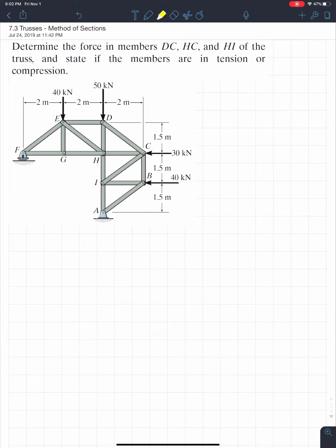That principle, specifically, is that when we analyze a joint, we want to create a free body diagram of that joint. So we cut all of the members around that joint. What you're going to see in the method of sections is that we do the same thing. We're going to cut the truss, and wherever we cut, whatever members we cut through, we replace those members with forces. Then you get a nice free body diagram with a bunch of forces based on the members that you cut.